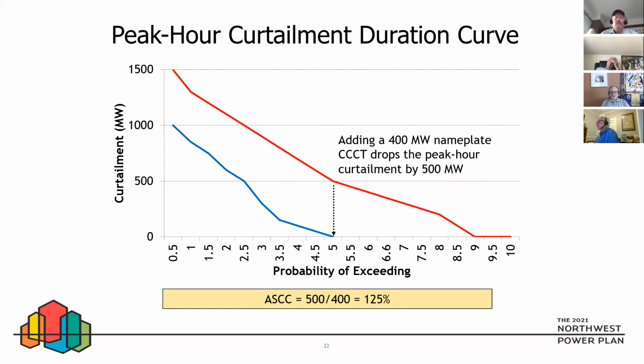assuming that prices allow it, and assuming that the hydro system has the flexibility, if you have a combustion turbine and if it's committed and if you can run it at night, you can run it at night and save water, and then the next day, not only do you get the full capacity of the combustion turbine, you get that extra peaking capability from the hydro system. And so the net effect is you get more than the nameplate capacity as a net